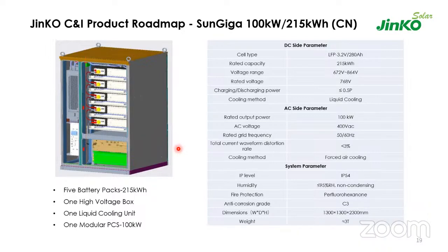Like, assume that your solar PV power plant is coming with DC, and you want to connect that DC with your charge controller segment to charge your DC cabinet solutions in a DC-DC application, and then use that as a backup for your backup load options, probably you can utilize that. But the only thing is that with DC-DC or DC coupled configured solutions, you will have better round trip efficiency, and it is limited only to specific capacity.